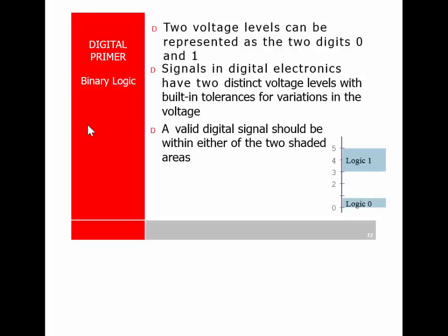A quick example of that, I'll give you a simple little circuit here. A very simple little circuit where here's our 5 volts, here's the resistor, here's ground, here's our push button, and this is our input to our microprocessor, or microcontroller. When you push that button, you take that point to ground.